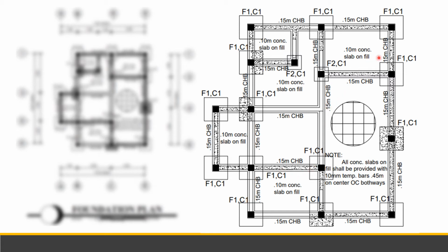So, there are also designs na yung outer walls is 15 cm and yung mga inner walls is 10 cm. So, depende sa gamitin nyo. But you can also use yung 10 centimeters sa lahat ng magiging wall mo, outer or inner. And also, nakalagay yung 0.10 meter concrete slab on fill.